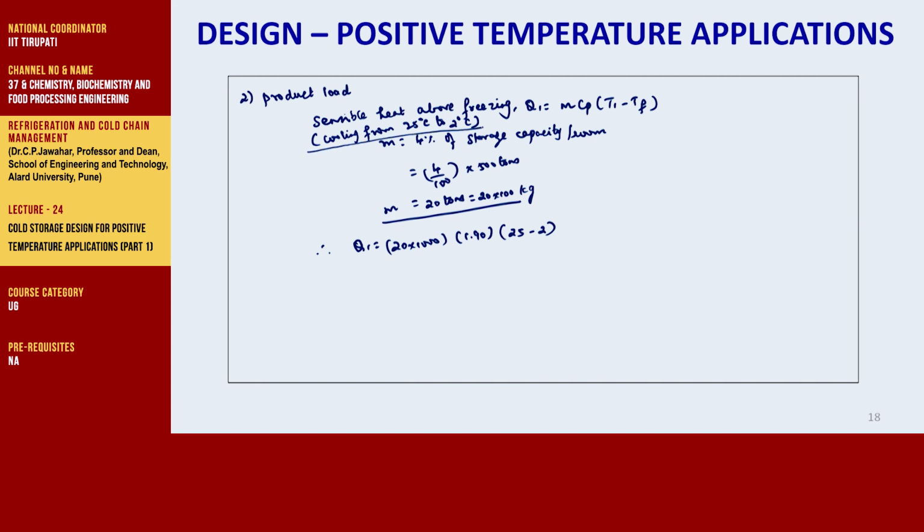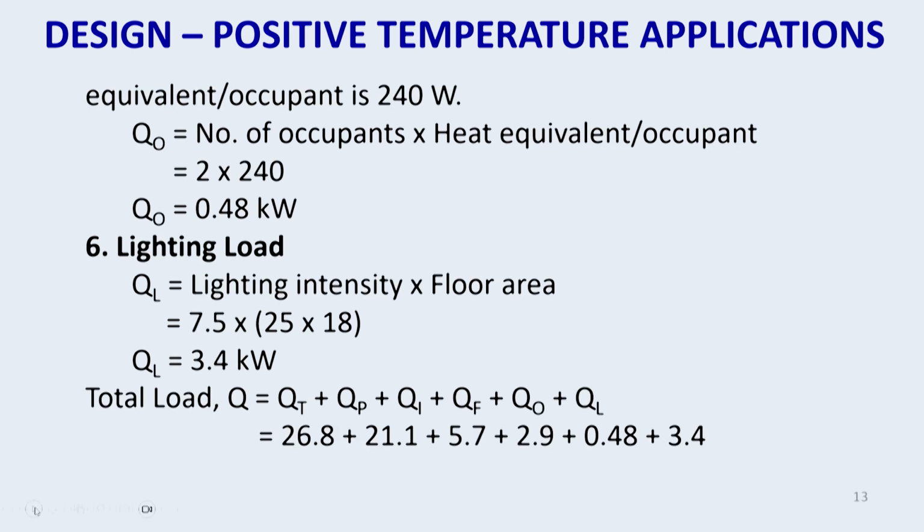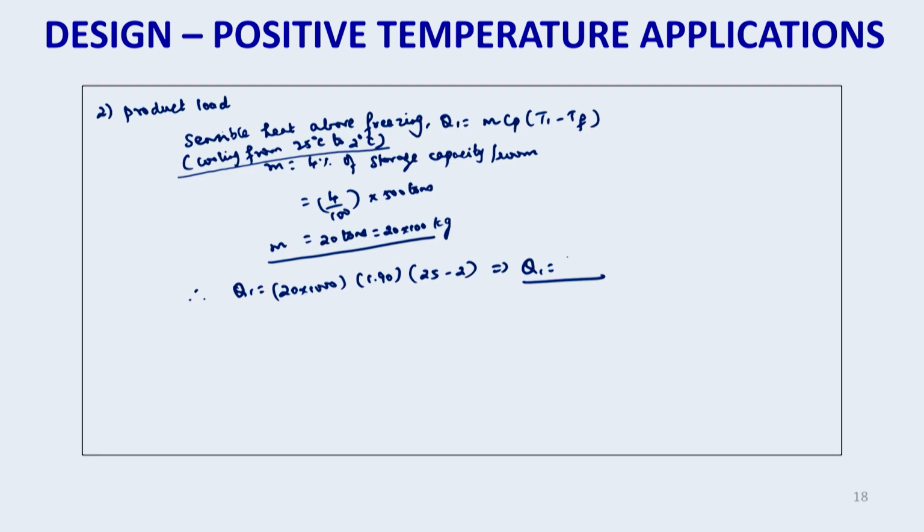If we calculate, the sensible heat load comes to 8,74,000 kilojoules per day, because the 4% of total storage capacity, which is the loading rate, is per day.